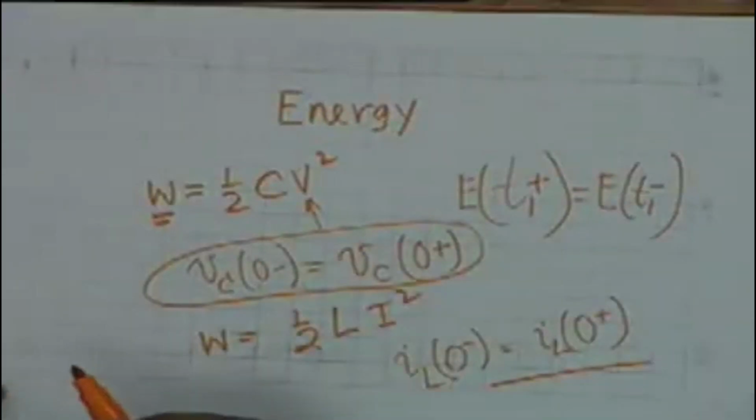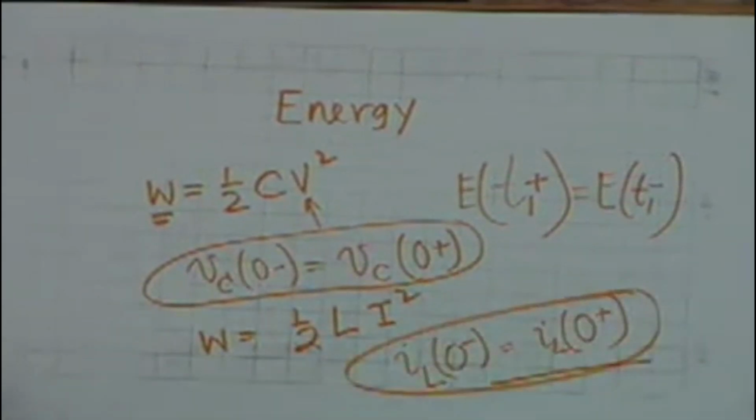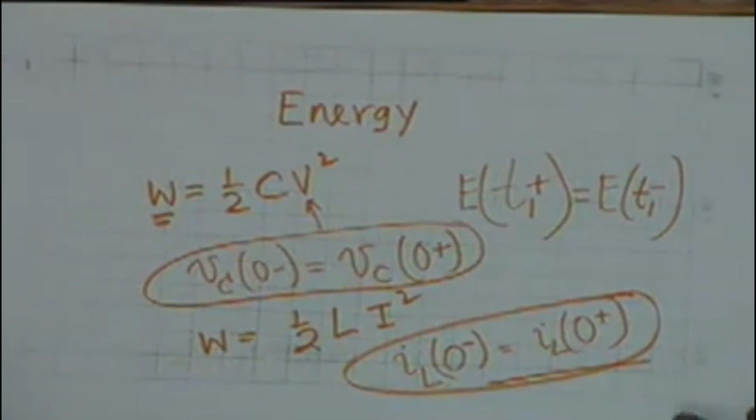These two principles, that the voltage across a capacitor cannot change instantaneously, and that the current in an inductor cannot change instantaneously, will be extremely useful in the analysis of circuits, electronic circuits or otherwise.